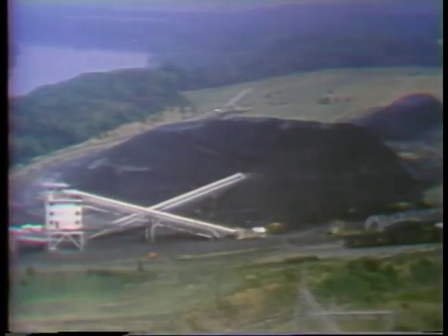We can now calculate the efficiency of the unit. Efficiency equals energy out divided by energy in. And we know the energy out, that's electrical power generated, which is 26,550,000,000 foot-pounds. To figure the energy in, we must calculate the amount of energy contained in 4.2 tons of coal.